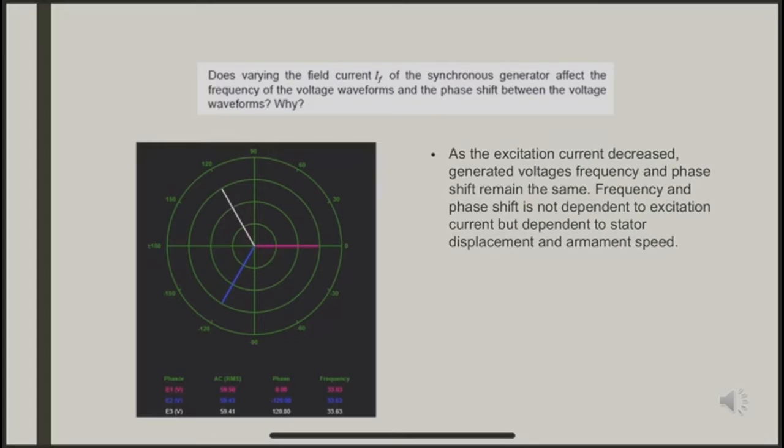For this question, the answer is the same as for the first question, because the phase shift is not dependent on excitation current but is dependent on stator displacement and armature speed.